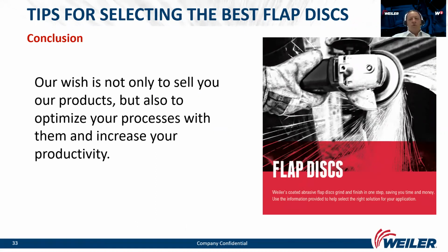Because if we do not have enough power, the cloth in this flap disc will not wear out properly. And the temperature of the ground surface will go up. And when the temperature goes up, then the burnings start, and the grinding is finished.